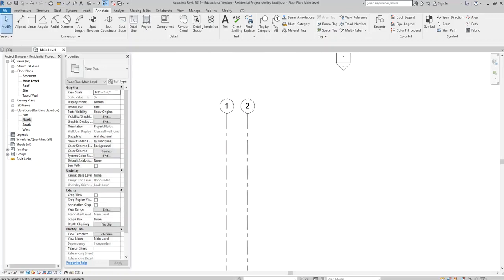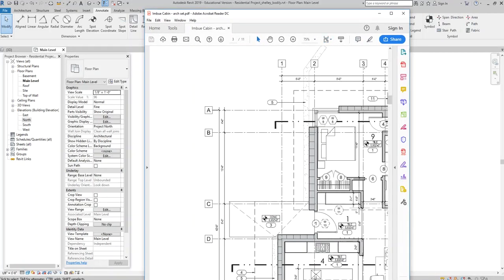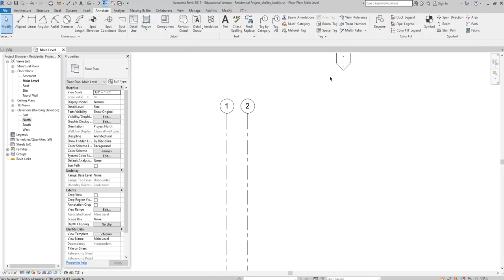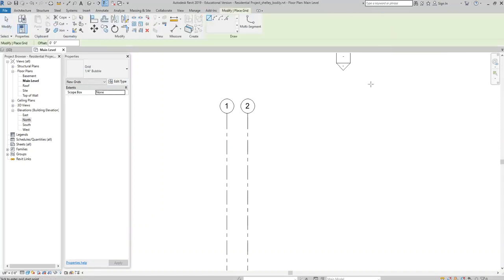Well, I have another grid over here. Number 3, and it's 9 feet away from the second one. So I'm going to go back to grid, architecture, grid, which is GR, and that was 9 feet, so the offset is 9 foot, enter. Click on my pick, click, there's my grid, right?